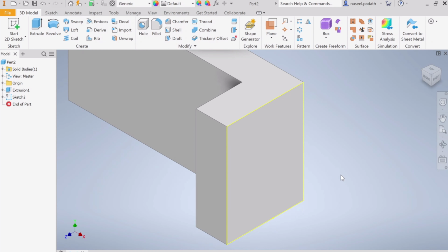Why? Because you can see when you project the geometry, the entire geometry of the 3D object is projecting all its side edges. Because if you want to make a sketch over a 3D object, once you create a 3D, the software recognizes that body as a 3D object, so you're going to be confused about where the edges and corners are and so on and so forth. So it is a must to project the geometry so that you can easily pick the corners and sides and all. So you can see now it is projected.